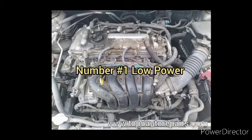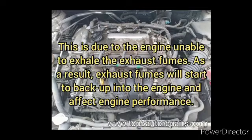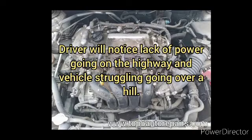Let's talk about the exhaust system fault diagnostic procedure. Number 1. Low power. When the exhaust system is blocked, the engine will have low power caused by excessive back pressure in the exhaust system. This is due to the engine being unable to exhale the exhaust fumes. As a result, exhaust fumes will start to back up into the engine and affect engine performance. The driver will notice lack of power going on the highway and the vehicle struggling going over a hill.